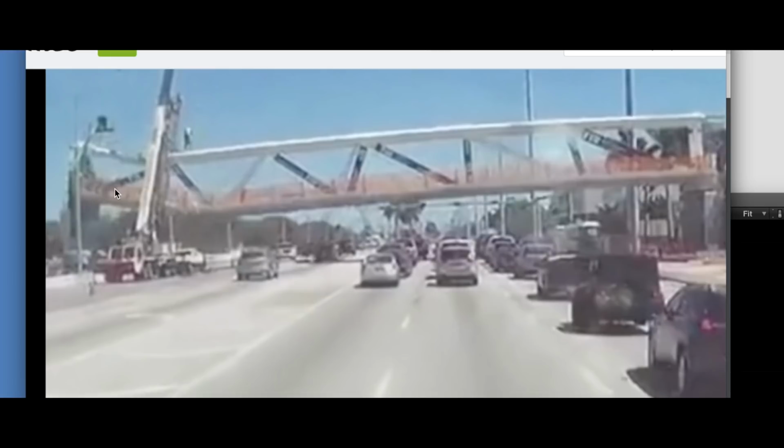Number 11 right now has a post-tension bar in the deck. The post-tension bar was, visually, from this node to here. You can see where this would now tear apart number 11, if 12 is no longer working at this point. It would tear apart the top of this section here on our number 11.